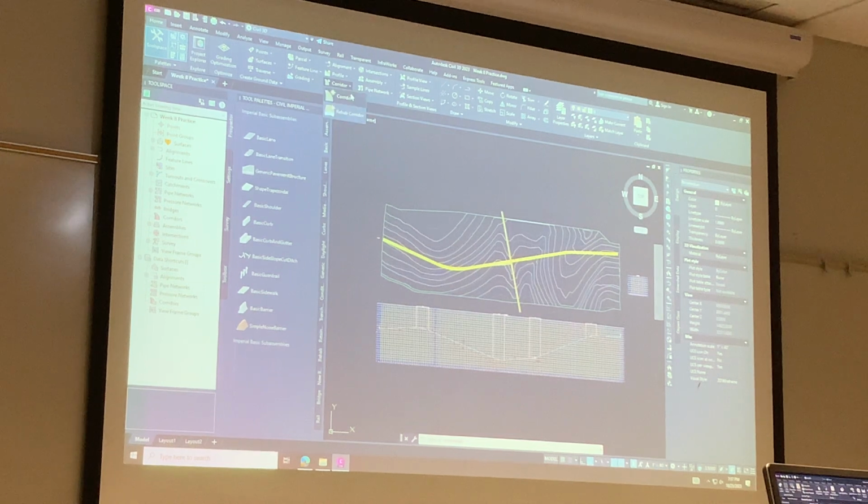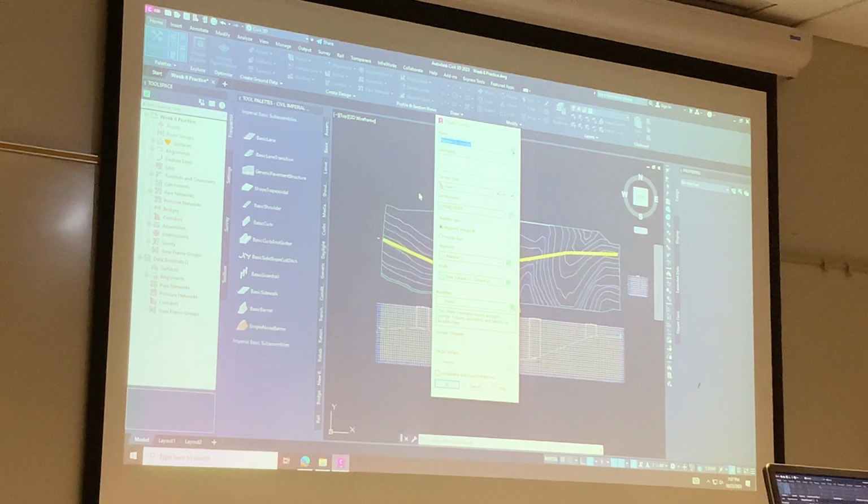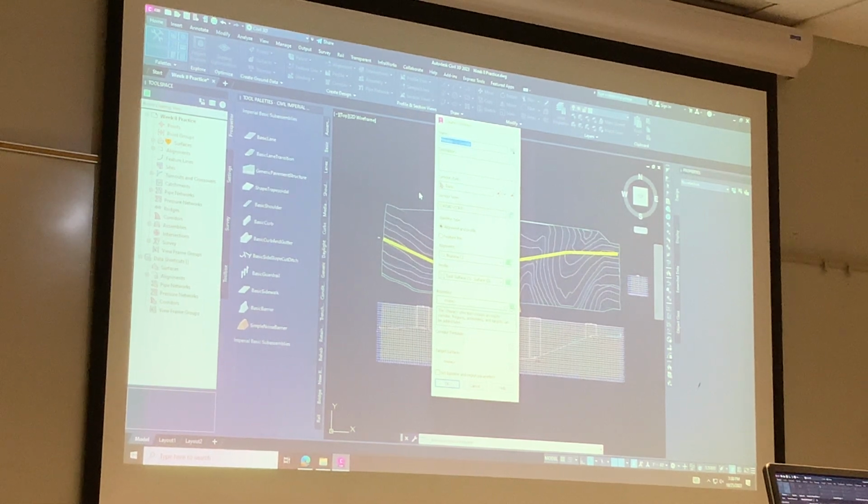All right, and then after adding super elevation, we created our corridor. Actually, I got a lot of exclamation marks on my stuff. Why? I got giant orange triangles. Okay, hover over one of those giant orange triangles and tell me what it says. If you hover over it, it should say something. Oh, there we go. Minimum K for stopping sight distance. Minimum K for stopping sight distance. Okay.